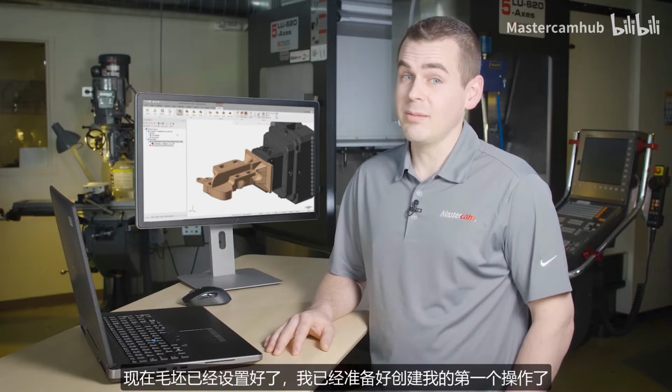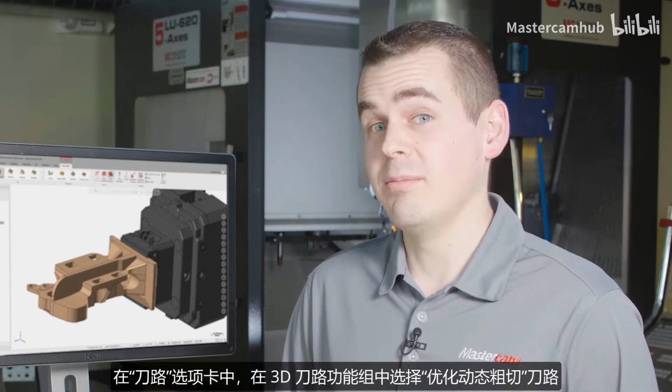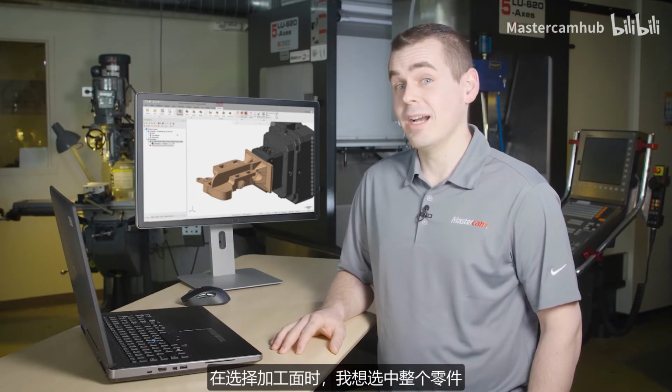Now that the stock is set up, I'm ready to create my first operation. For my initial roughing operation, I'm going to go to the Toolpath tab and select OptiRough from the 3D toolpaths. For my machining surfaces, I'm going to select the entire part.